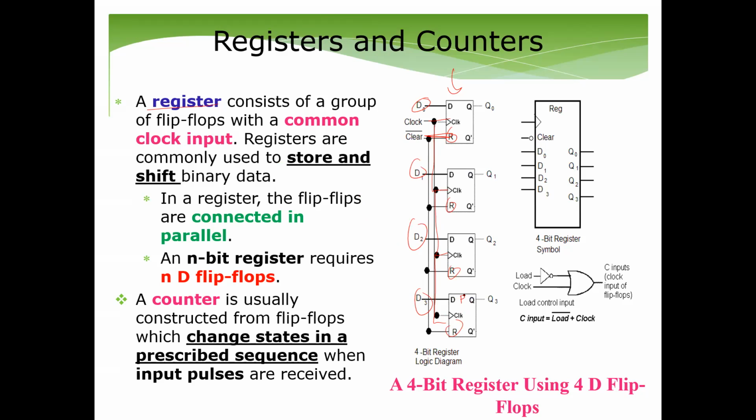Imagine that you have a preset here. All these have to be common as well. Any special signal has to be common between all flip-flops inside this register, and a common clock and a common reset. It will have different data input and different data output.